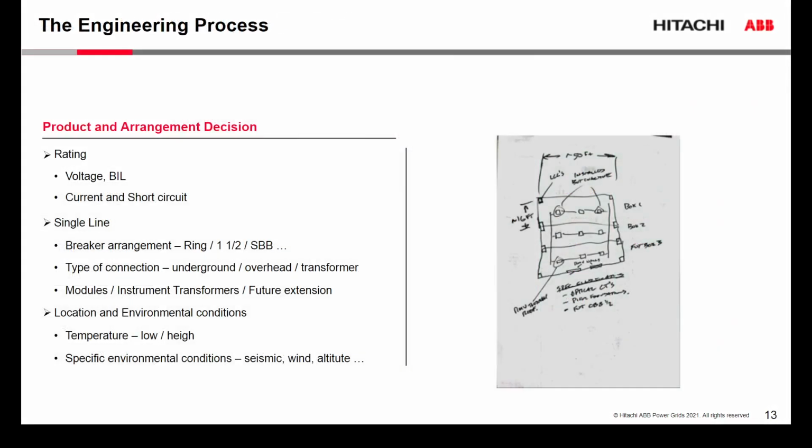With all that technology, how do you make your decision what is the right product and how to move forward? If you are seeing on the right side, that is not the worst, but also not the best of what we received on a request, showing a number of breakers and requirements. It is of course good to know the ratings of the equipment. That means it's good to know the voltage level to start with, and it's also good to know the current and the short circuit current of the equipment, as that will, for example, define certain changes in the technology used